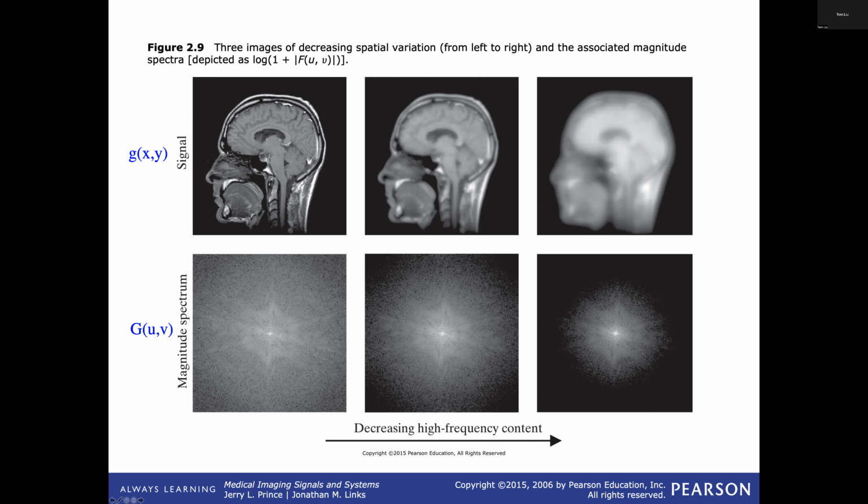Other things will be like, if I'm sampling this Fourier domain here and I take 10 milliseconds to get all my samples across here, but the object I'm imaging, the signal decays away very quickly, right? So as I'm sampling, the actual amplitude of that signal is decaying away. And so what that will do is it'll affect how I sample this Fourier transform.